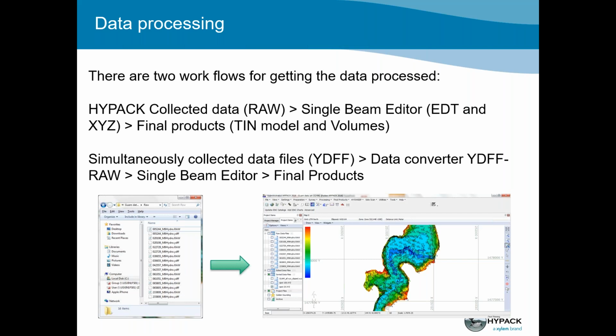Simultaneously, we collect the SonTek raw data file, which is called the YDFF. The YDFF cannot be read by HYPACK directly. You have to convert it before you can use it. So in HYPACK, we have a data converter that converts the YDFF into raw, and then you can put it into the single beam editor and final product as well.